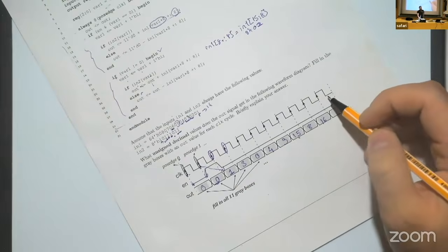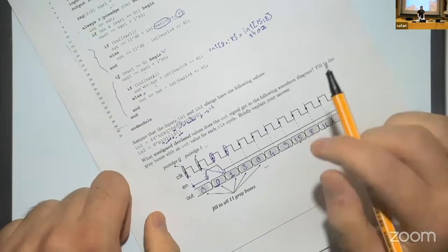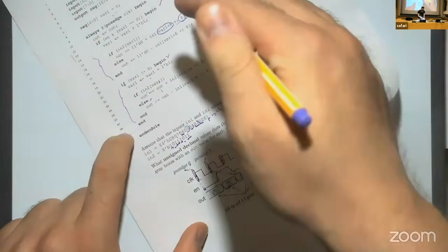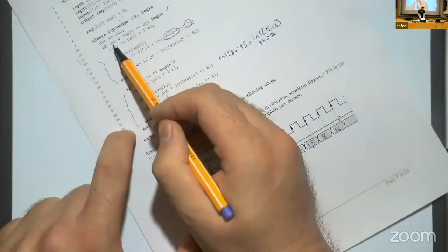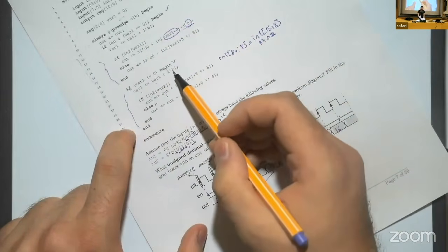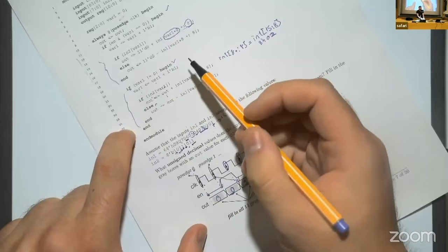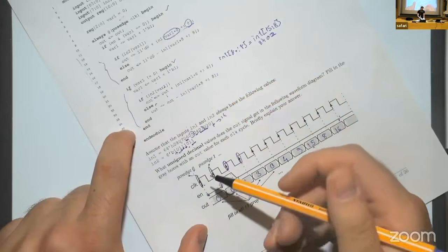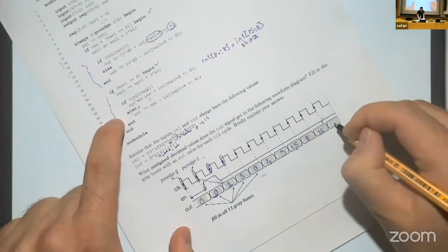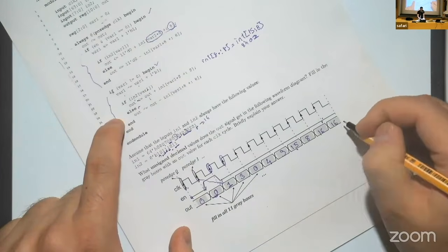Now, in the last cycle, we know that var1 is 0, and you see that enable is also 0. Enable is 0, so we don't go into that block. And var1 is also 0, so we don't execute that block. It's the same as the first cycle. So output will get the same value as the last cycle, which is 16.